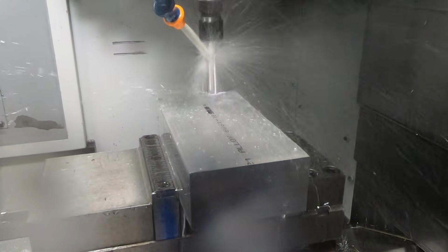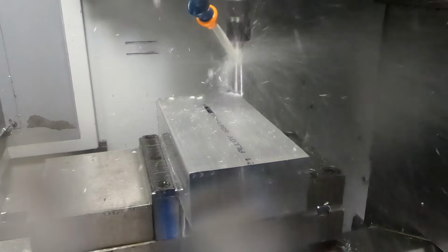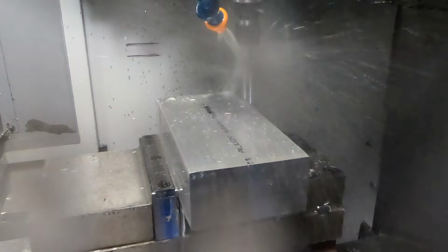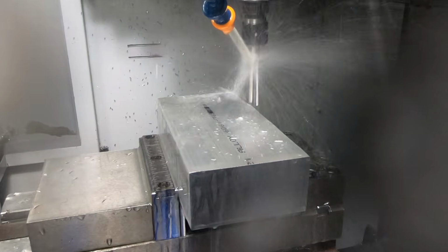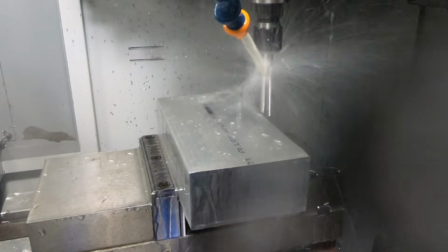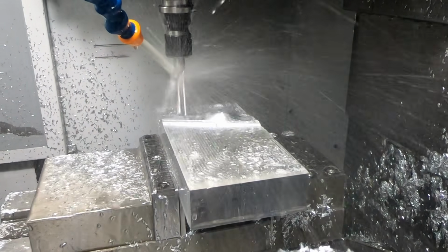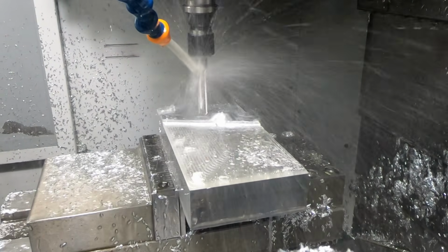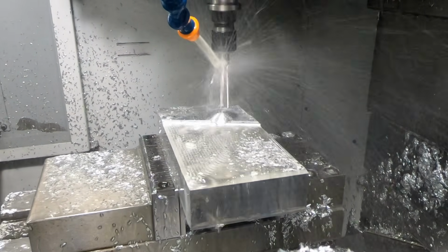I realized I was using a cut that was too aggressive. This machine suggests much lighter cuts, so I stopped it. And then picked up again with a new toolpath that was less aggressive. This is part way through the roughing, and you're starting to see part of the spoon, the bowl itself, start to appear.